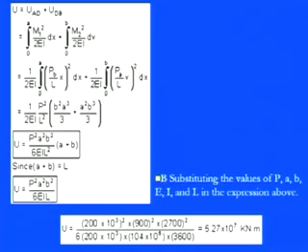So we have 0 to B, P A by L into the x whole square into dx. After doing this simple integration, we finally have 1 by 2 EI P square by L square B square into the bracket itself. After keeping those values for the limiting conditions 0 to A and 0 to B, we have B square A cube by 3 plus A square B cube by 3.